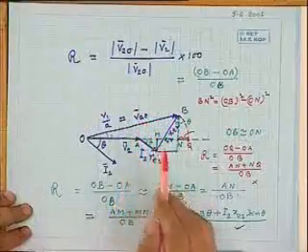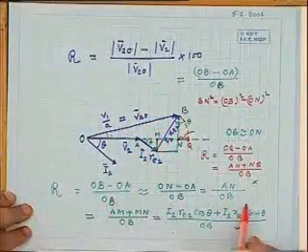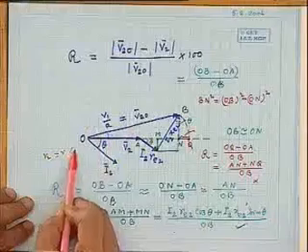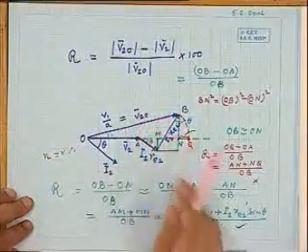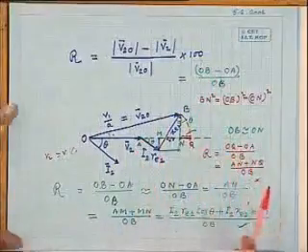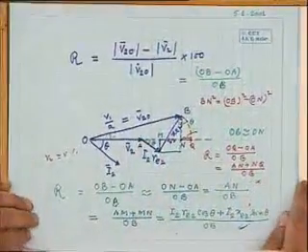And another thing I want to remind you is that while solving a problem, don't start making a phasor sum here to get V10. Try to exploit this simple equation to get those readings. You will often be tempted to take V20 as some magnitude and angle, and add these two drops like that. But you will arrive at the same results, but after so many calculations. Are you getting? The more accurate result will be V20 plus I2 bar Z2 bar. You get V1. Anyway, next time we will